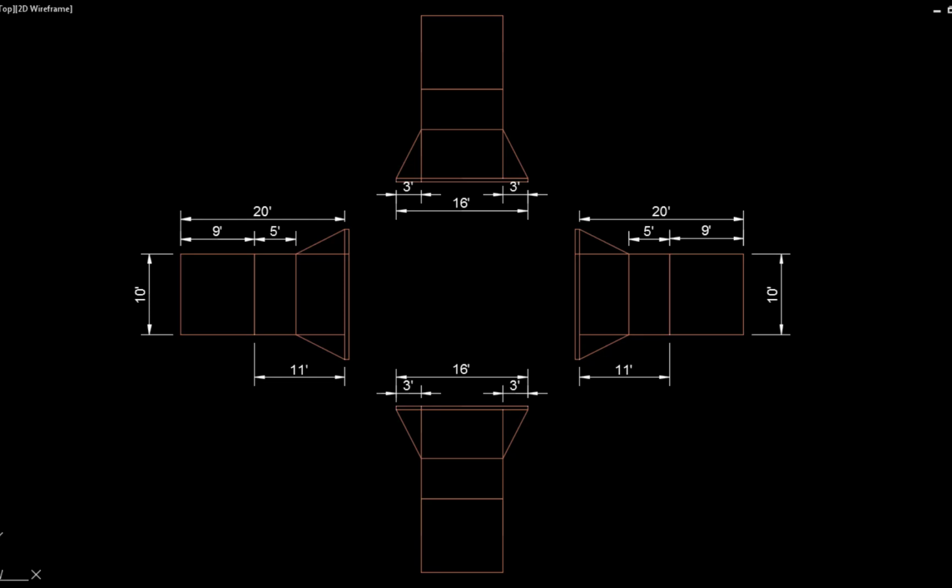Prior to inserting a template, a copy of the template is made. The width of the template is stretched to conform to the width of the existing driveway, and the length of the driveway section of the template is stretched to conform to the length of the driveway reconstruction improvements. The AutoCAD Align command, AL, is used to insert and align the driveway template to the curb.